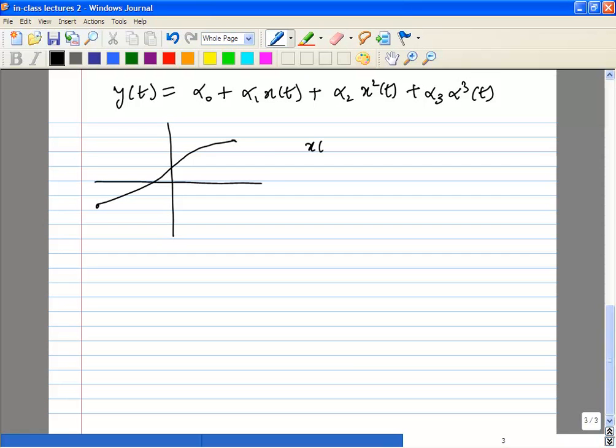Okay, and let's assume x of t is... one of the first things you do when you're measuring IP3, so in a real case your interferer could be much higher than your desired signal. But when you measure it in the lab, you want a standard way of measuring it across many systems. So what you do is you give 2 tones with the same amplitude. We'll assume it's a cos omega 1t plus a cos omega 2t, and we'll assume that omega 1 and omega 2 are nearly equal.